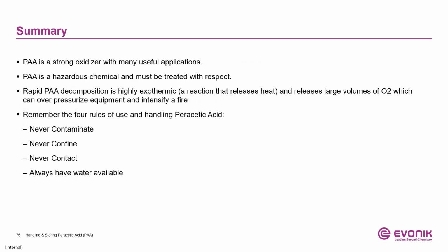In summary, you have seen how PAA is a strong oxidizer with many useful applications, but it is also a hazardous chemical, and it must be treated with respect. You have also seen that rapid PAA decomposition releases heat and large volume of oxygen, which can overpressurize equipment and intensify a fire. Remember the 4 rules in the handling of peracetic acid. Never contaminate, never confine, never contact, and always have water available.